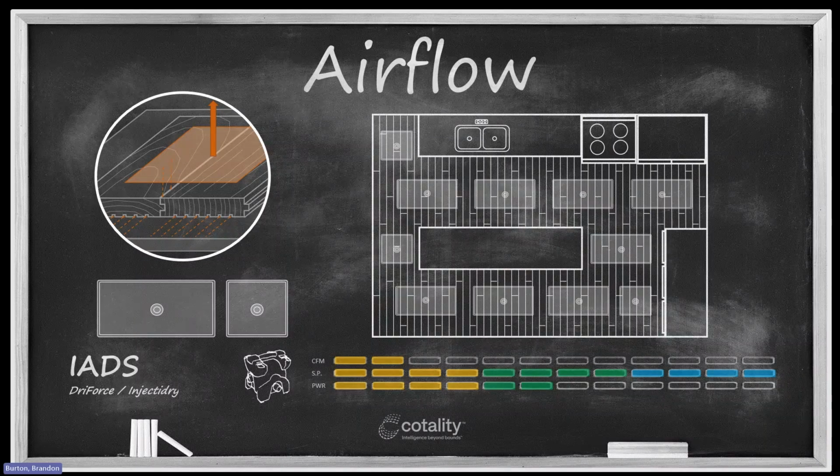The mat is creating suction. That suction is going to result in flow through the flutes. The flutes are parallel with the boards. If I'm perpendicular on the floor, I will affect more flutes. Every mat will have a larger effective footprint because now it is causing a negative pressure on more flutes underneath these boards, through all of the tongue and groove joints that are underneath the mat. That's the first thing I want you to observe.